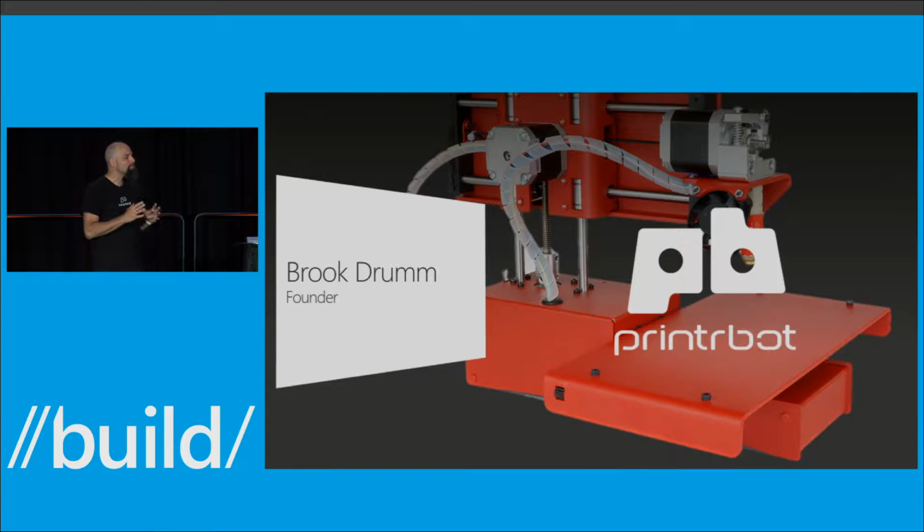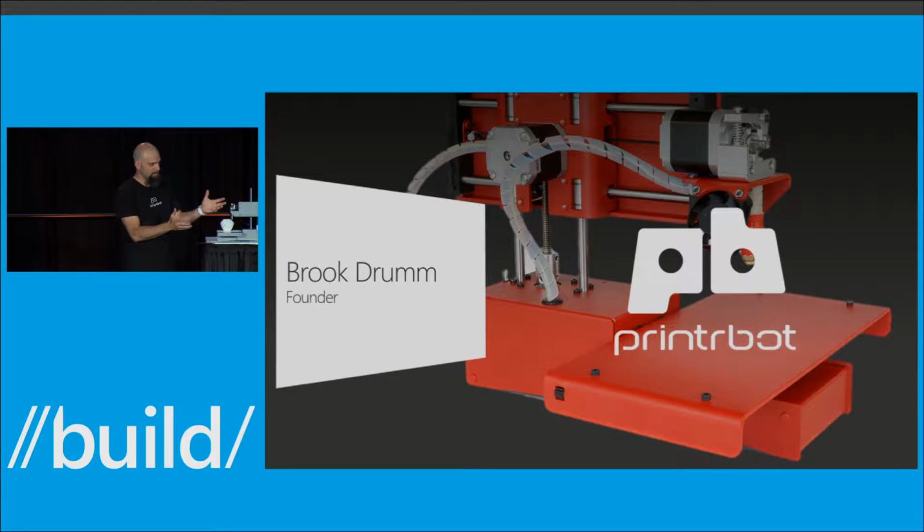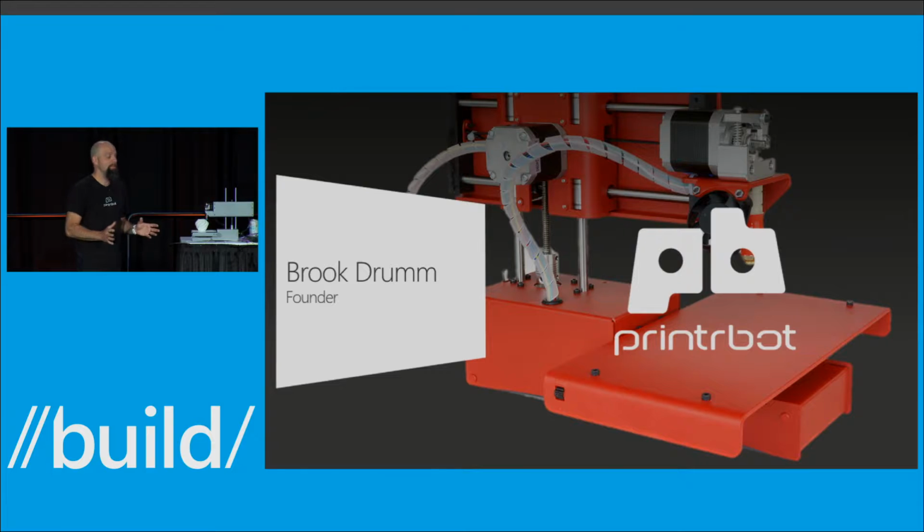So I'm thrilled that the software is getting easier. But this Metal Simple, or the PrinterBot Simple, it's $599, and that is assembled. This is easier to use than it's ever been for us, for sure. These 3D printers sometimes can be finicky about leveling the bed and whatnot, but we've got this auto bed leveler. In the firmware, it probes the bed, and it can tell you where this plane is, so the software can figure out where to print. And when it's printing, it's adjusting the height of the nozzle. If it's going downhill, and these are slight differences, right, it moves the z-axis.